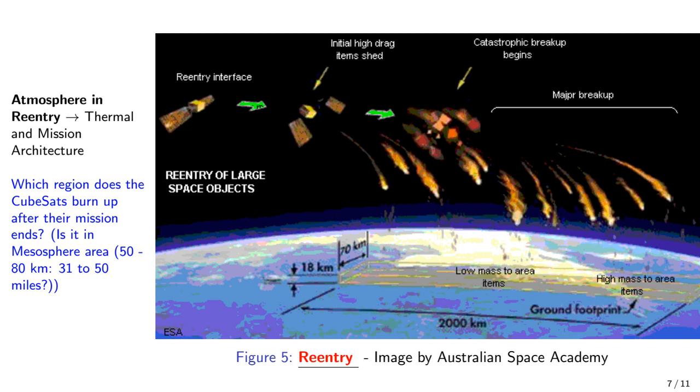That's in your mesosphere layer, let's say, close to your thermosphere. Okay, so it's not your stratosphere. And this is termed the re-entry interface. Time from breakup to impact is from 6 to 30 minutes. The length of the re-entry footprint mostly depends on the re-entry process above 50 kilometer altitude. The width is also affected by tropospheric winds.